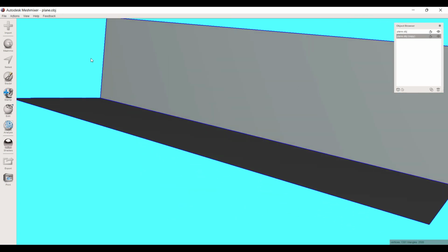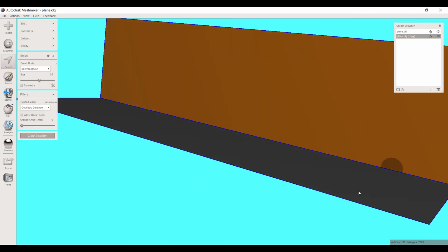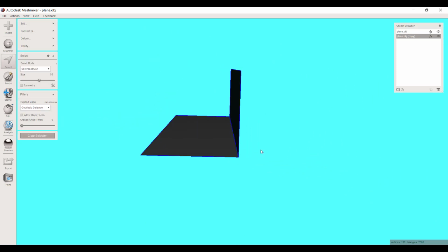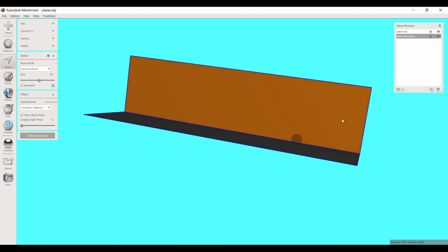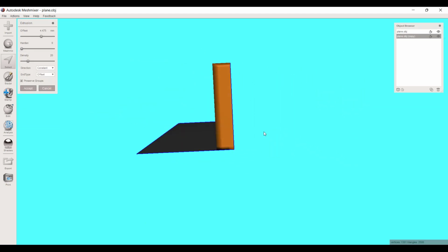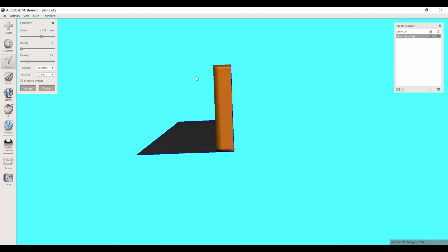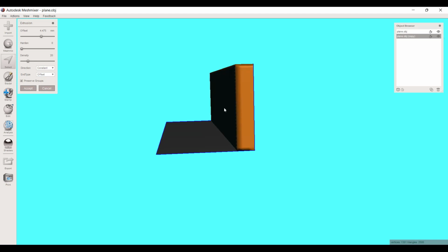Well, I could just select all. I could either use the select tool and select this whole thing, or I can use the hotkey Control A. And what I want to do is extrude it. So under the Edit pop-out menu, you see Extrude. The hotkey listed is D. If I hit D, again, this is where it becomes really useful if you're working in the global framework, because it's not shooting off in some random direction. It's going to extrude outward exactly in the, what would that be, the Y dimension.